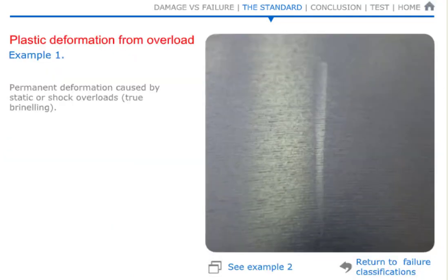Overload results from static or shock loads and leads to plastic deformation. Now, this can be recognized by depressions at rolling element distance. Often, wrong mounting procedures are at the base of the problem. In other words, applying the mounting force to the wrong ring and thereby producing a shock load over the rolling elements.